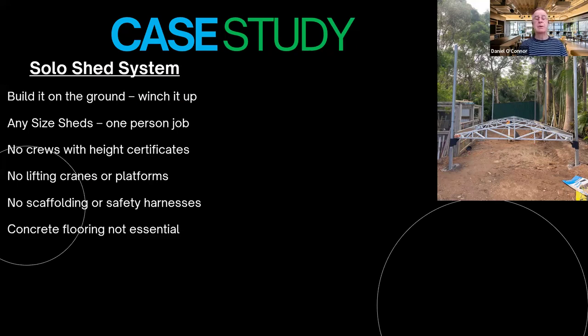In fact, if you're in a tropical area, you can actually put the roof up and then tilt the walls up using the same pulleys and winches. Once you've done that, you can then pour the floor. So it means you're not subject to weather in any way. There's also no coordinating required for crews or rental of equipment or the weather even. So all of this is doable at any time.